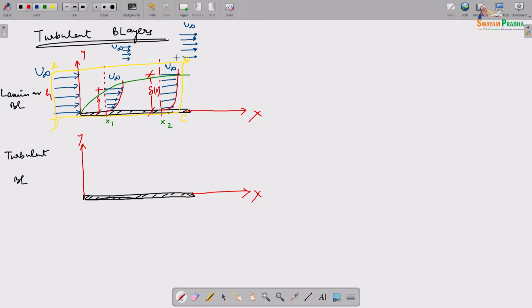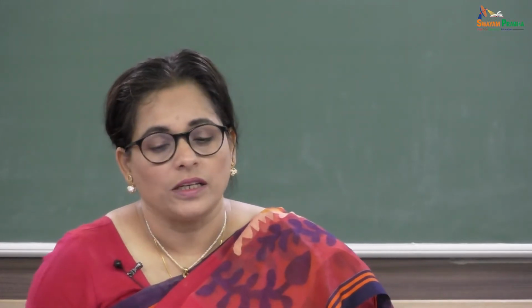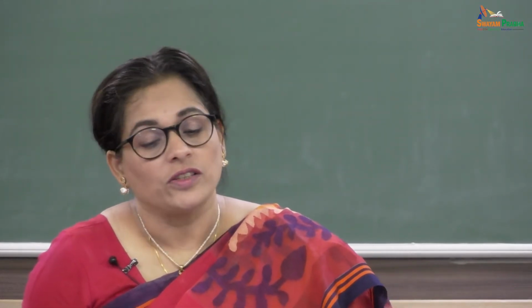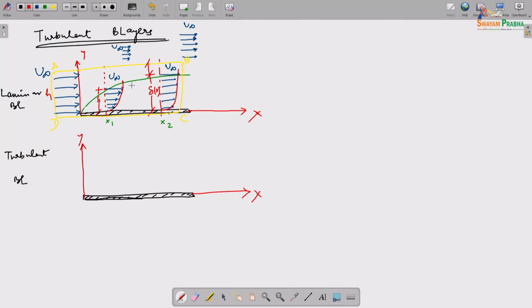So, therefore, we take a height across, in the y direction of the fluid, where the velocity will be the free stream, and if I add that to the momentum across the velocity profile here, then that should add up. Right. So, that extra height is what is called the displacement thickness, right. Let us just say that height is this, and I am going to call that, and as you can see, that height is also a function of x, right.